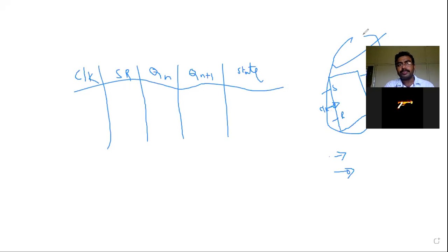You already know how to denote the circuit diagram for the SR flip-flop, and we have already seen the operation with the help of the gated SR latch. Let me explain how the states will be with the help of a truth table. Guys, if you are using positive edge triggering, a positive clock to trigger, your clock symbol should be shown like this in the truth table always. If you are using positive edge triggering to change its states, you should use this kind of symbol for the clock. Or else, if you are using negative edge triggering, the clock will be denoted like this.